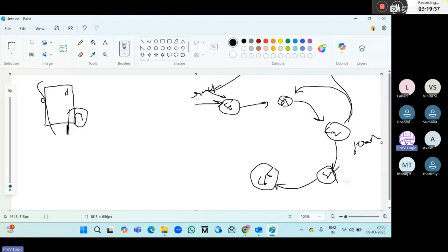Okay, then also we will get the error. The amount is not available or transaction failed, that kind of error will come. So again, it will go to the previous state. From the previous state, again we need to re-enter. If it has the re-enter option, it will go to the previous state. Or else it goes to the reset state. Okay, suppose whatever amount I have given is correct, then it goes to S5.